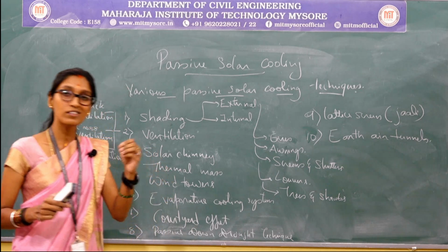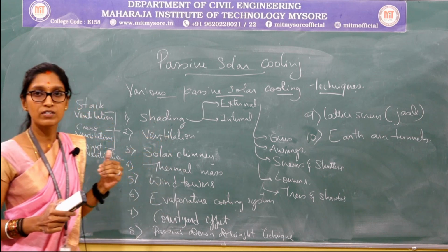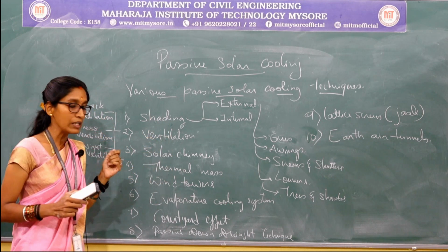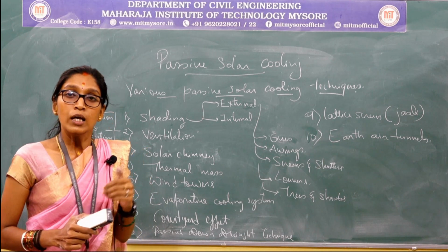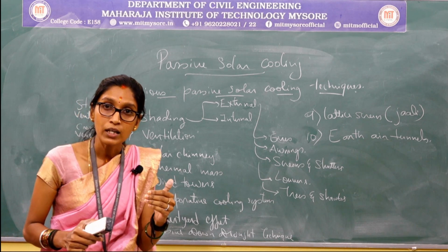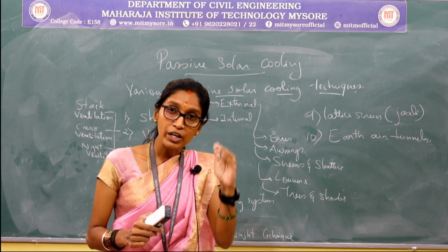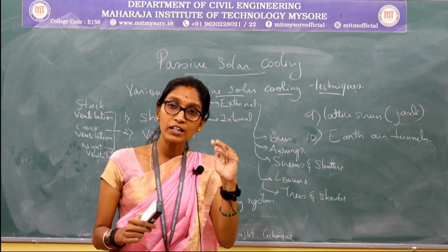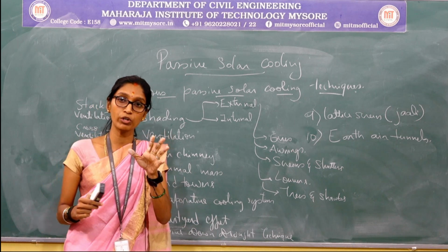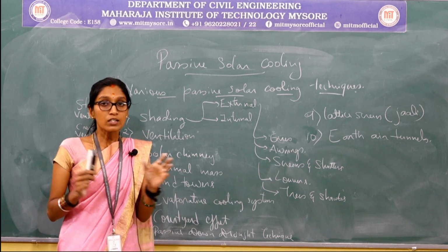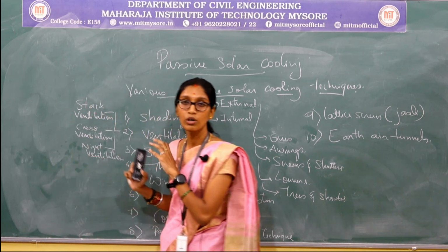Now, how do these vents help in providing the ventilation, right? And how does the air exchange happen in these various ways? So, in the case of stack ventilation, what happens is that, based upon the thermal difference in the air or the pressure variation or difference in the air, a thermal buoyancy comes into the picture, and that is the major principle on which stack ventilation runs.